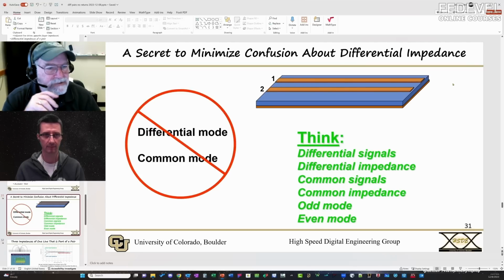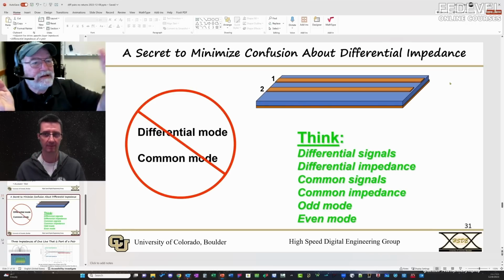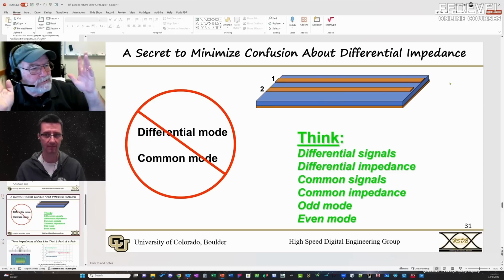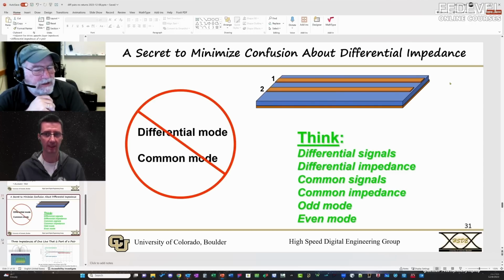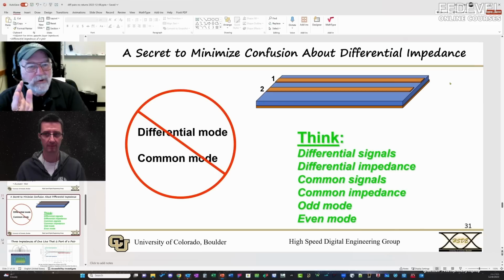It's only if this gets onto unshielded twisted pair or an external cable, because it's going to be an antenna, a wire sticking off, and the return will be somewhere on the floor, that it causes radiated emissions. So it's only in certain special cases that common currents are bad for EMI. Otherwise, we have common currents all the time on circuit boards, and they cause no real problems.